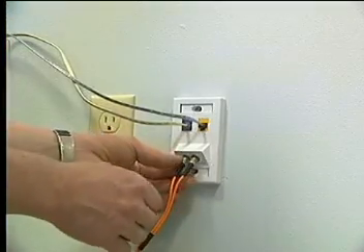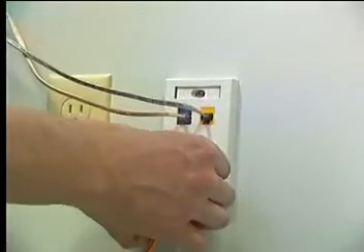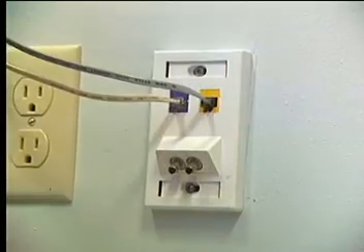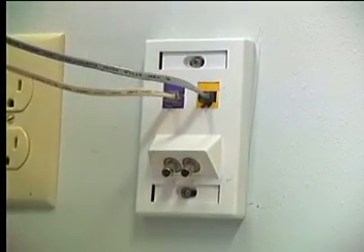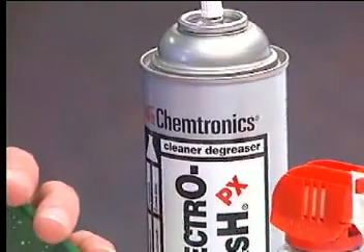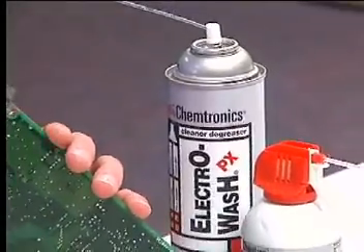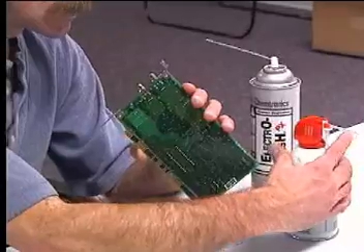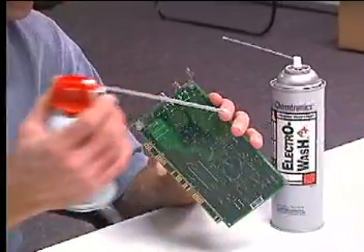Connectors that cannot be accessed from both sides can be difficult to clean. These include media outlets, as well as transmit and receive ports on equipment or circuit cards. This means that the optical surface must be cleaned while in the connector sleeve. The first step is to blow out large particles using a canned air duster.